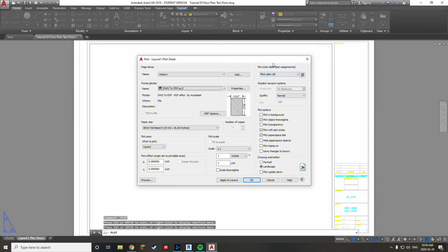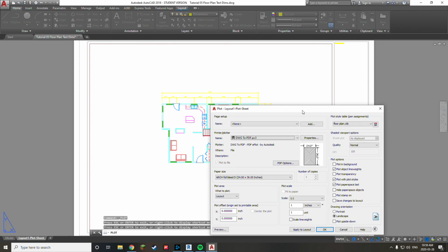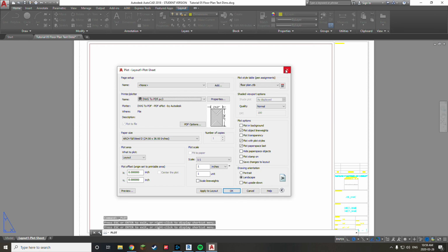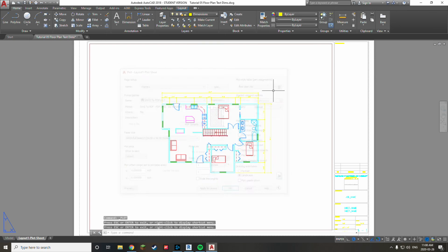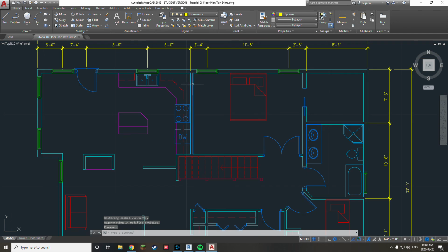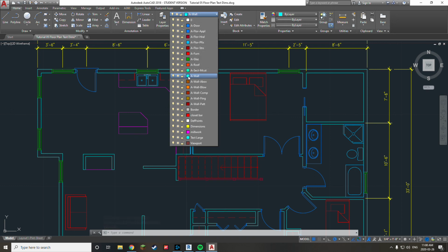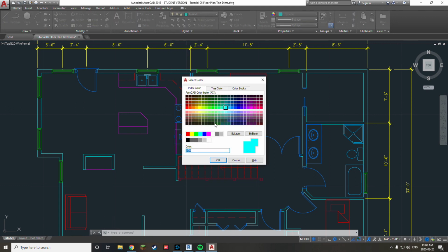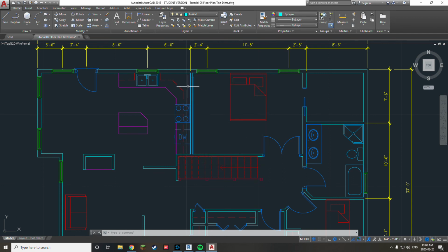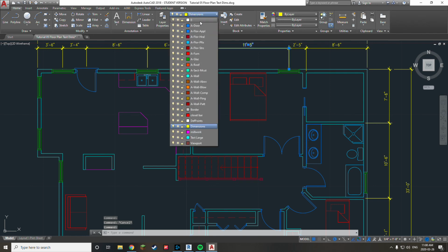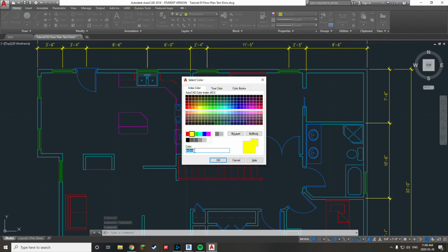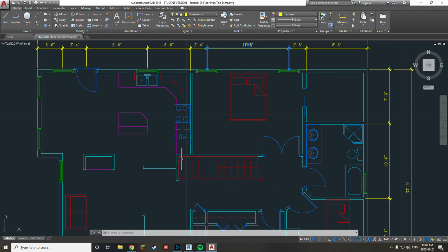So beyond that, the real work for you is to figure out what colors you used for, let's say, your walls and for your dimensions, and then we'll just change those two basic colors. So I'm going to hit cancel here for now and backtrack. I click on the wall, layer name says A-wall. I click on the little colored square here, and it tells me that my walls are color 130. Wonderful. Make note of that. Dimensions are yellow. It's probably color number 2, which is yellow. There it is. Great. So those two colors for me are going to be a little bit different.